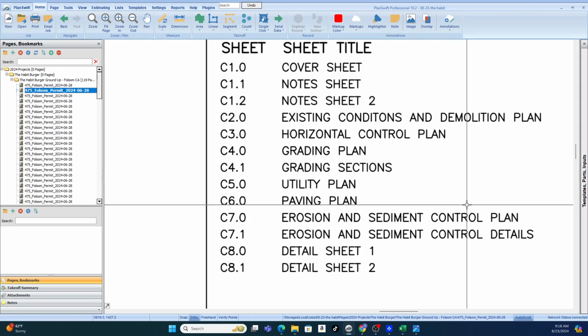Okay, so excavating and grading are two different types of operations, but we're still dealing with the dirt. We're excavating, getting it out of there, making it smooth, pulling stuff out, putting stuff in, but then we go and we grade it to where each of the curbs, gutters, manholes have to be at a particular depth or width or height within the dirt, and it gives us all that information.